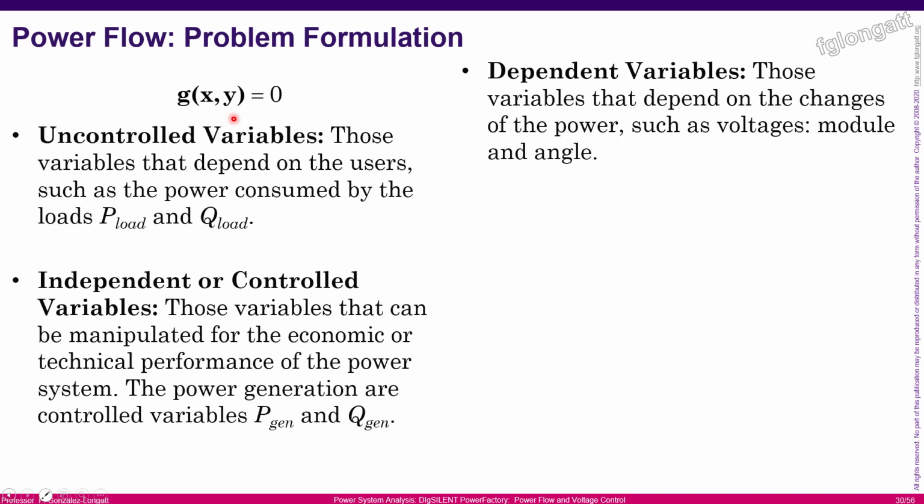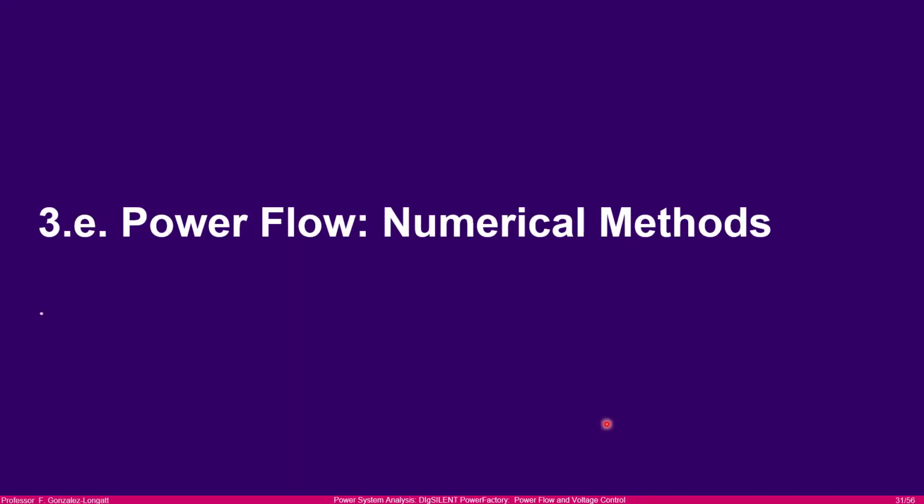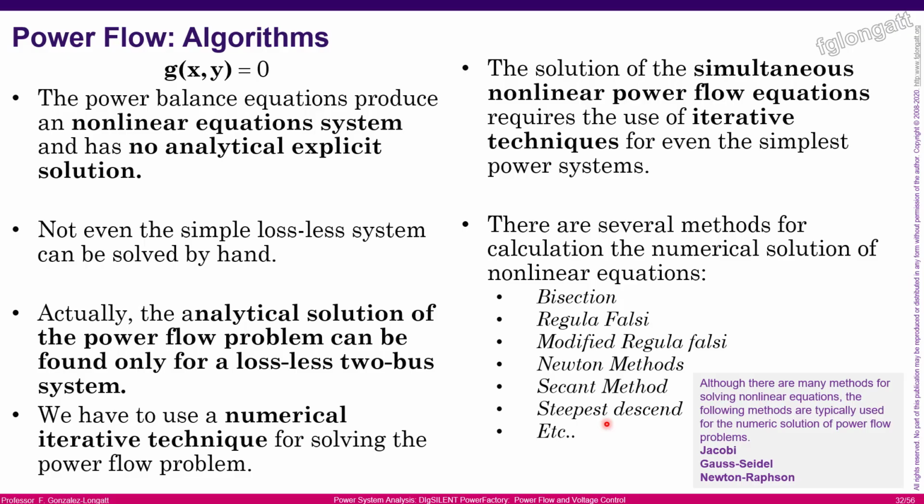But coming back to my explanation, the core of the load flow, the core of the power flow is the power balance equations. However, we demonstrate that those equations are nonlinear. And any power system analysis software is formulating the set of power balance equations based on the data that you provide to the software. In this case, the nonlinear equations don't have an analytical solution. They don't have a closed form solution. Even for the lossless case, solving those equations by hand could be time consuming, okay?